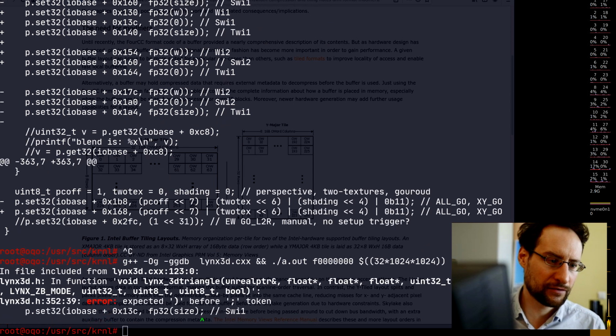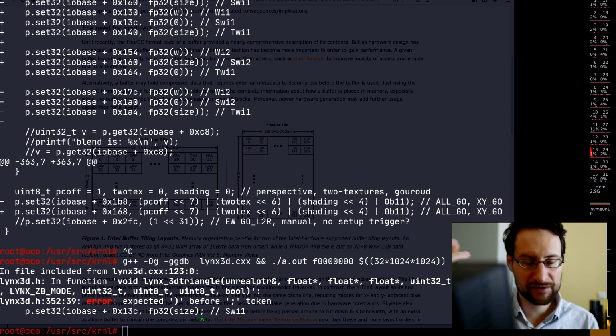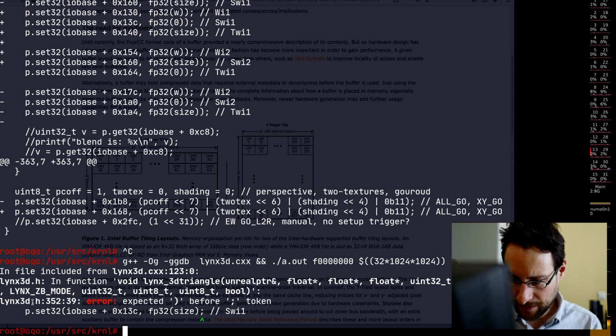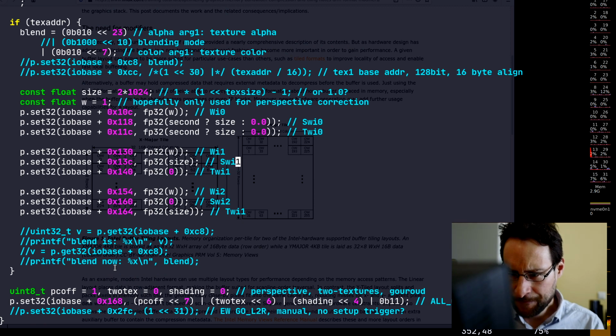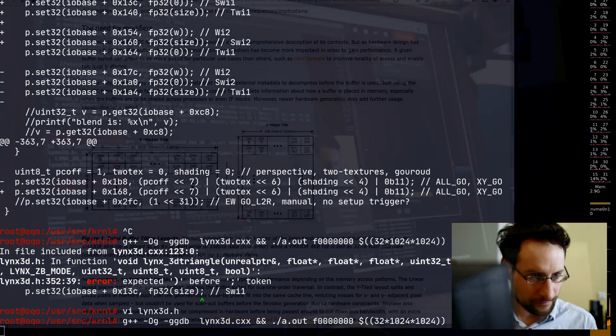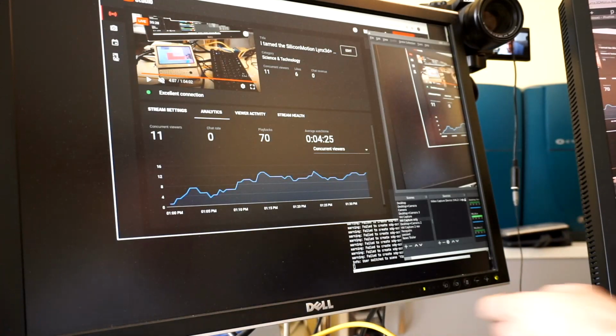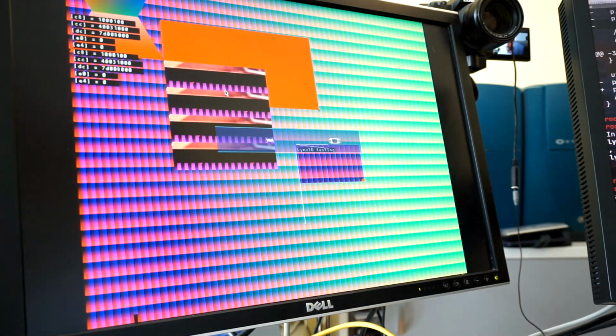And just another testament of not only often underdocumented, but even the hardware might sometimes do. I really wonder why they have not mentioned the tiling and swizzling here in the documentation. Also we have an error in line 352 of size, of course there is a parenthesis missing. And let's see. So this is how it looks when S and T are flipped.